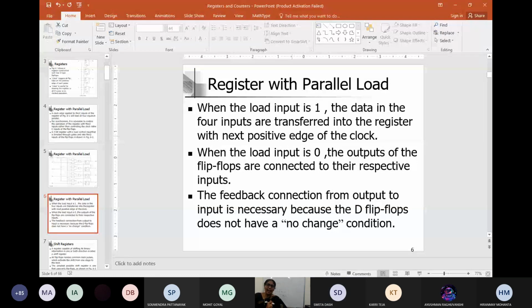Right. Now hold on. Can I have all the information at a stretch dumped into that? Okay, that is a pretty big task, because I have to collect all the information, and then at a time it has to load. It is really tough. Shift registers will go bit by bit only. That is definite. Now tell me, let us consider each bit requires 1 clock pulse to transfer. That means each clock pulse is dedicated for one transfer. So now 4 bits have to be transferred. How many clock pulses will I use? 4 clock pulses, no? So to transfer the entire information into this, I require 4 clock pulses, isn't it?